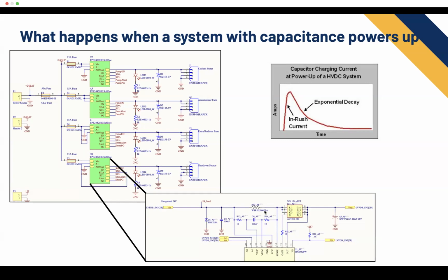But this 24 volts, it's going to go through R12, the sense resistor, through this MOSFET once the chip closes it. And then we have this 330 microfarad capacitor on the output. And that 330 microfarads is very large, but that's what this chip recommended we use to keep our power rails stable on the output. But that's not just on this one. We have 4 of these. So that's 4 times 330 microfarads plus 100 nanofarads. Now, in the face of 330 microfarads, the 100 nanofarads looks like nothing, so we can ignore that.